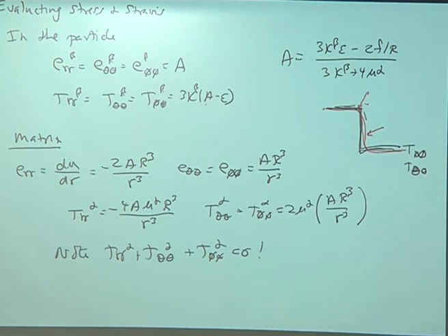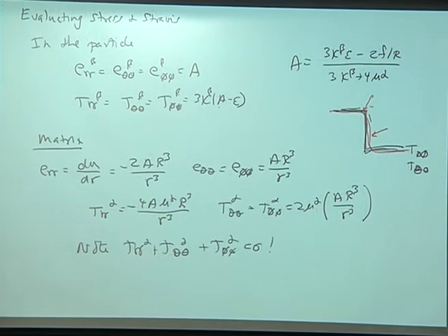Stress remaining inside the particle. Yeah, I knew you were going to ask that question. So let me think a bit. If this is 0, that disappears, this cancels, and you still have this epsilon term. You put this into epsilon, the epsilons cancel, and you get 0 stress. So you have no misfit stress. Okay, it works. You set that to 0, say F is equal to 0, so that's not there. The K betas cancel, the epsilon comes over to here and cancels, and you get 0 stress in them.